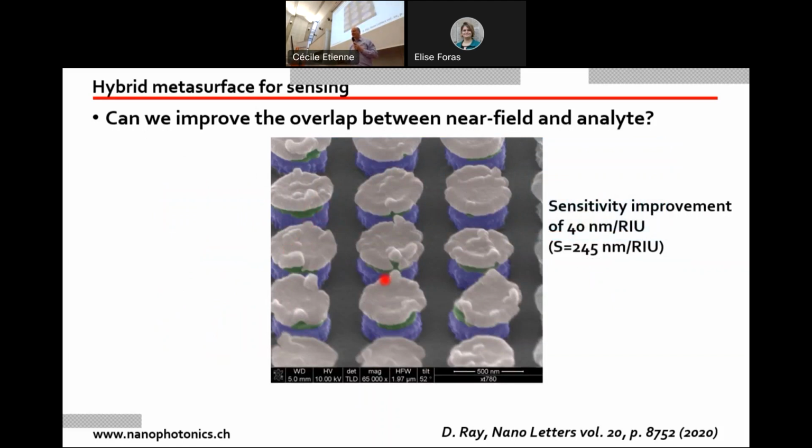So it's not cupcakes, it's really the nanostructure. You have silicone here in blue. In green, you have the glass spacer, which is now a bit narrow. And on top, you have the aluminum. The aluminum is not very pretty, that's typical. Aluminum is very grainy when you evaporate it. It doesn't really matter in that case because the field is mainly horizontal, so it doesn't probe this graininess. But at least we could fabricate it and we could measure it, and it was a bit better.